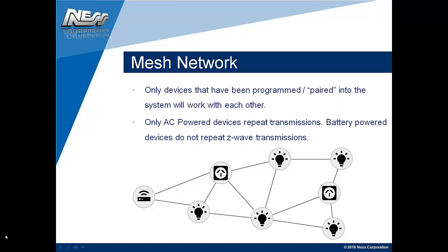From the gateway, you put it into a learn mode or program mode, and each Z-Wave device has a little program or learn button. When the controller is in learn mode, you select what type of module you're going to learn in, whether it be a smart switch that can just plug into a power point, whether it be a globe, or another smart switch or dimmer that can go behind a light switch in the wall. Once it's in learn mode, you just go to the device with it powered up and press its program button, and it then sends a learn signal, through frequency hop as needed.